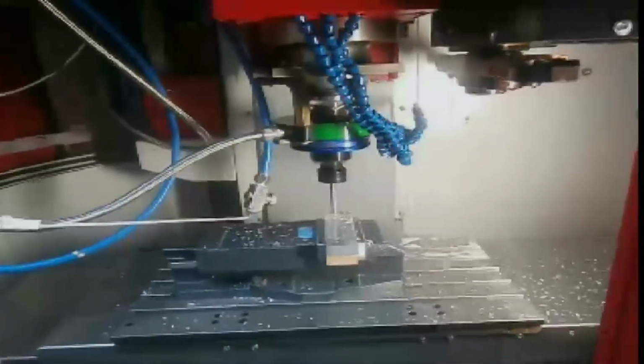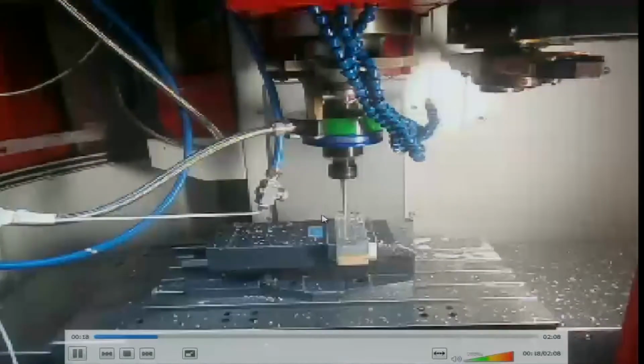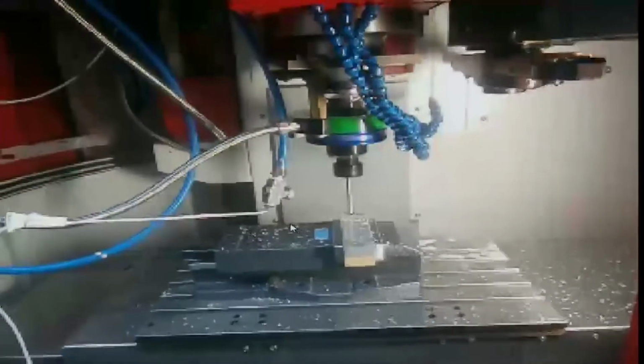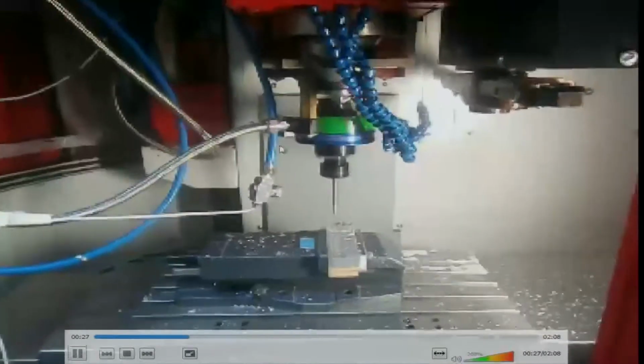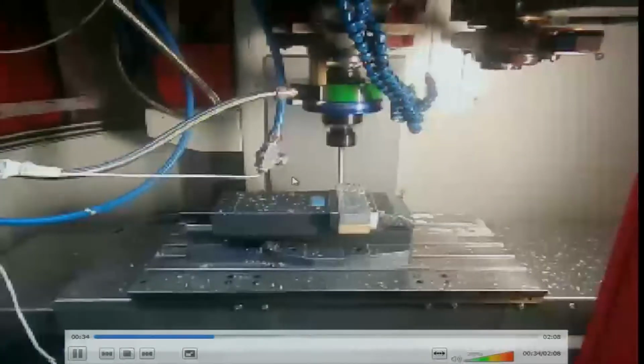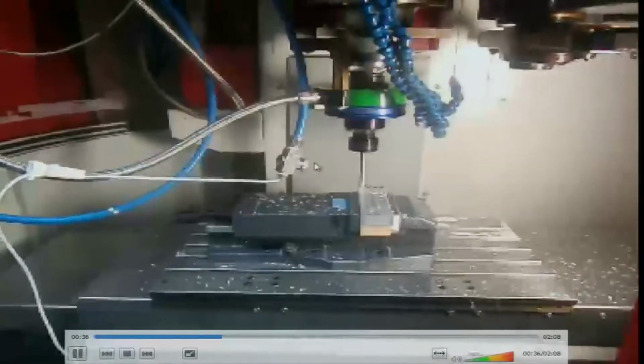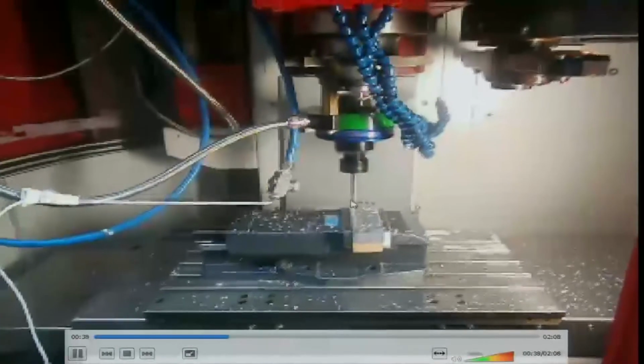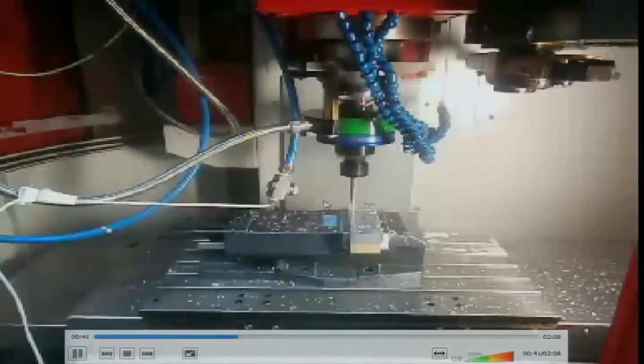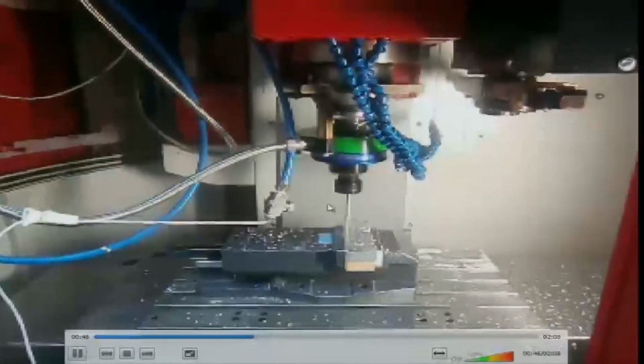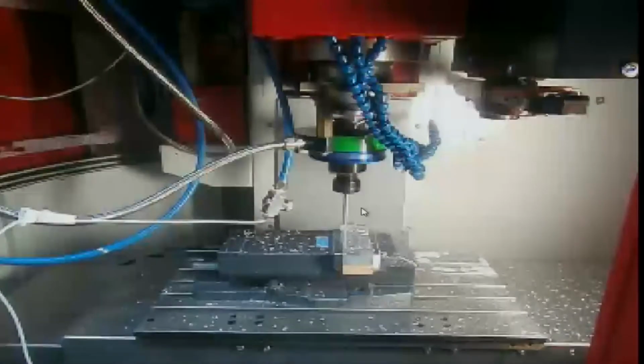I have a nozzle here that is spraying the fluid. In this nozzle, from the white pipe the cutting fluid is coming, and from the blue pipe on the top of the nozzle the pressurized air is coming. So we have the air spray or mist spray here, and this distance is also optimized. We can even keep multiple nozzles. This is only one nozzle, we can even keep 2 or 3 nozzles. It all depends upon the kind of machining we are doing.